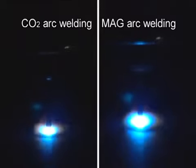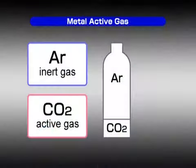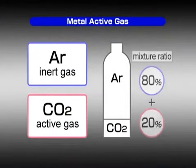But the arc characteristics of these two welding processes are different. We will explain these welding processes separately, respectively named the CO2 welding process and the MAG welding process. For the MAG process, it commonly uses an 80% argon, 20% CO2 gas mixture, and we will explain the MAG process under this condition.